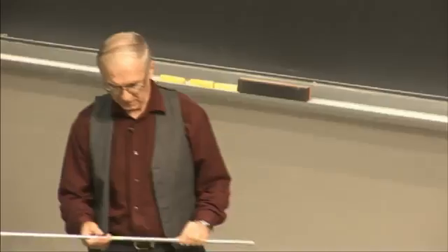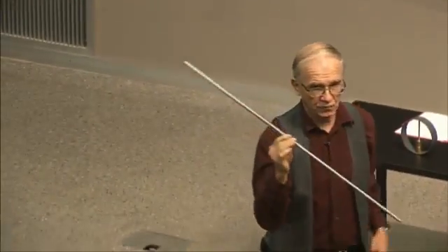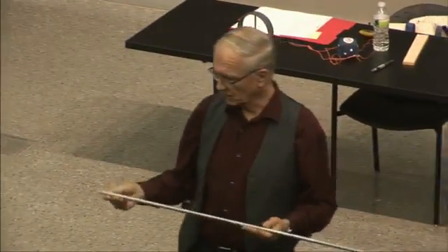Lots of things in real life, like this aluminum rod, will vibrate. And continuous systems, which this is, have a theoretically infinite number of degrees of freedom. Yet, when it comes to talking about its vibration, it is conceptually easy to think about the vibration of an object like this, one natural frequency, one natural mode at a time. And in fact, you can model that natural mode with its single degree of freedom equivalent. And that's the way I approach vibration. So if you can isolate one particular mode, you can literally model it as a mass spring dashpot. So you need to understand the mass spring dashpot behavior inside and out, because it's the vocabulary we use to do much more complicated things.